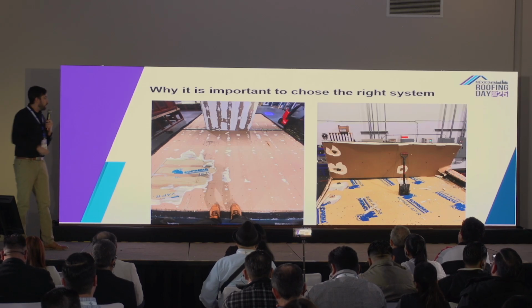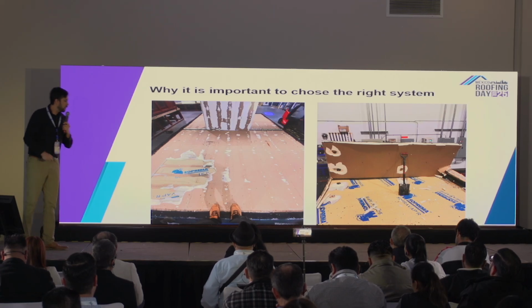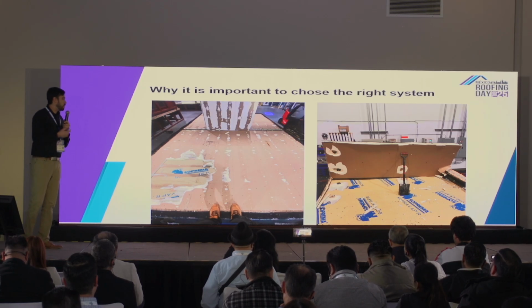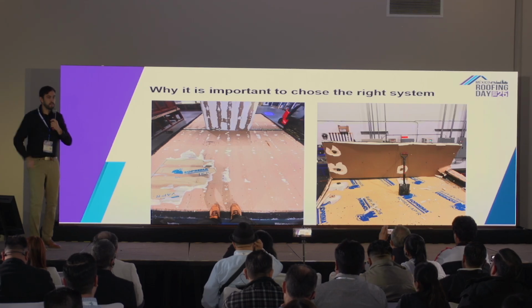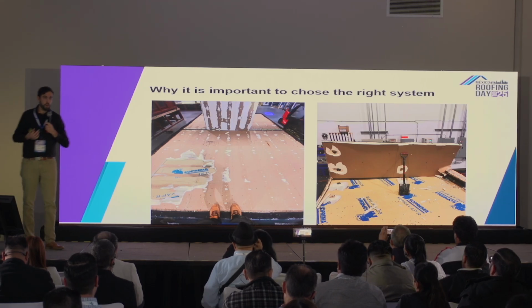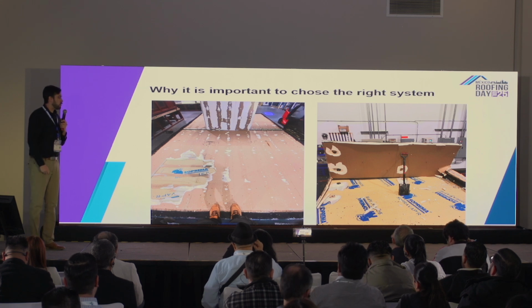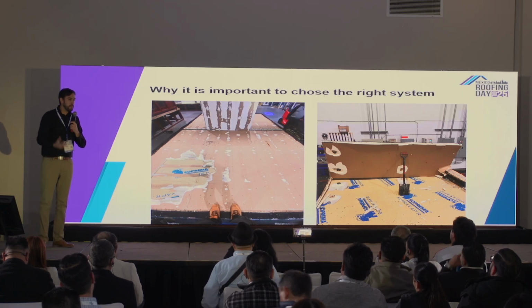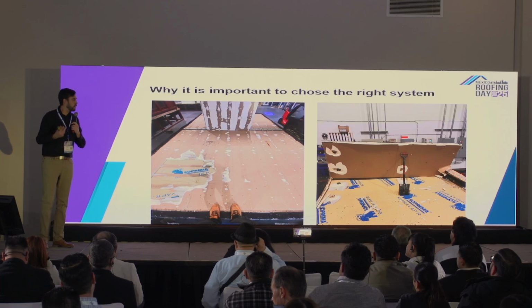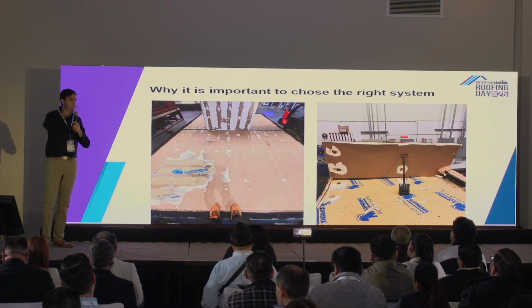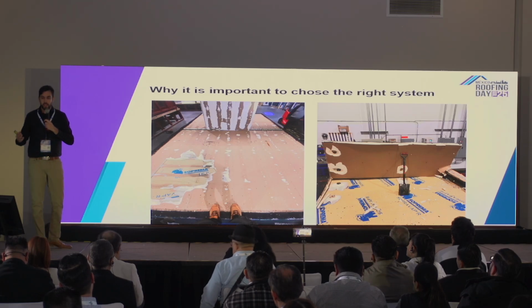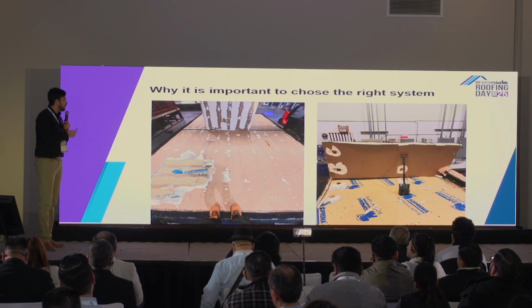What you see on the right is a pull-through. It means that the board went through the plate of the mechanical fastener. So again, think about the snowball effect. As soon as one of those fasteners lets go, the other ones are more stressed and more likely to go. Usually what we see when a test is happening is one screw pops out, it makes a really big noise, and afterwards it sounds like a zip. Pop, pop, pop, pop. Great noise, but it's pretty much how it always happens, those types of failures.